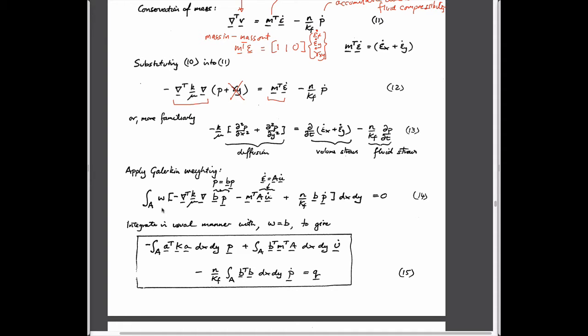I think this last step here is trying to do the Galerkin thing, but let's not worry about this, right? You weight it by some magnitude. For a weighting function, you do some manipulation. But let's not do that. Let's skip this step, because we don't care, and figure out exactly what this is. This is the conductance term. So it's going to be A transpose Ka operating on pressures. So this is our K matrix.